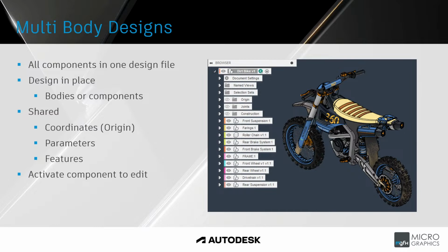At the top level, in this case the dirt bike V1, that top level assembly is active. The timeline for all of the components and sub-assemblies would be exposed, and you'd see the entire timeline for that design within the timeline in Fusion 360. So you would be able to scroll through the entire timeline for that entire assembly when the top level is active. But as mentioned, when you start to activate sub-assemblies or components, you would then only see the features related to those components.